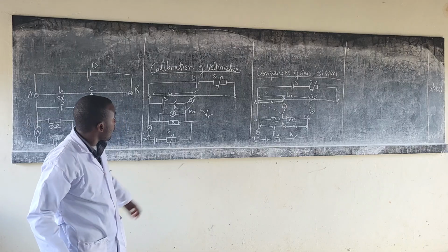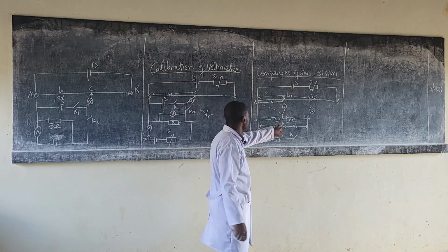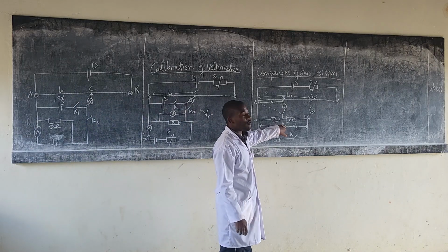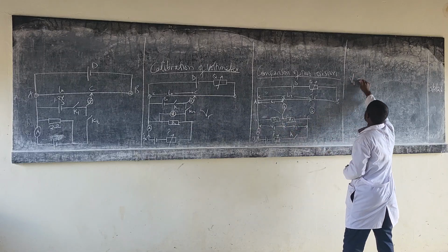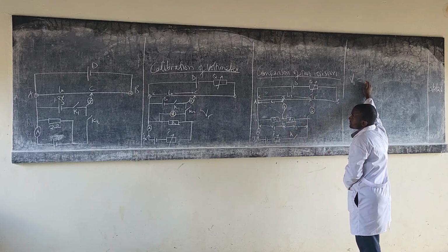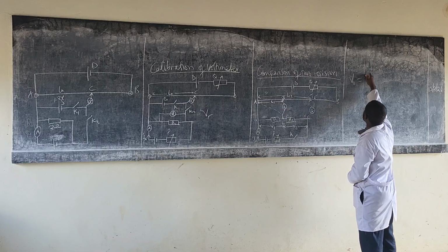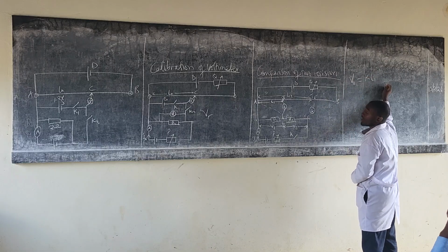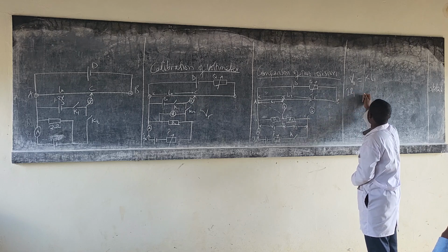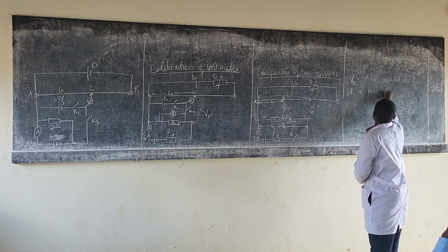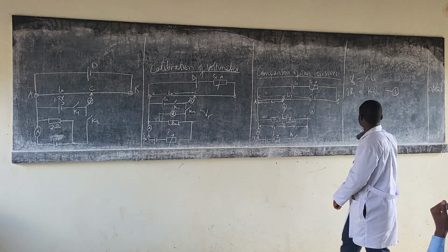Well, so when the jockey is at point B, what does that mean, therefore? It means that V1 equals what? Equals K L1, right? But V1 is I R1, which is K L1. Call that equation 1.